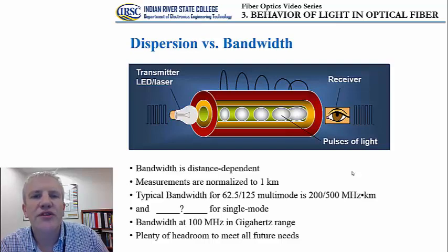As far as the mode theory is concerned, we've seen that light that propagates along the fiber can be represented as a set of distinct modes. And from that perspective, we categorize the optical fibers into two big categories: single mode fibers that support one single mode, and multimode fibers that support multiple modes.